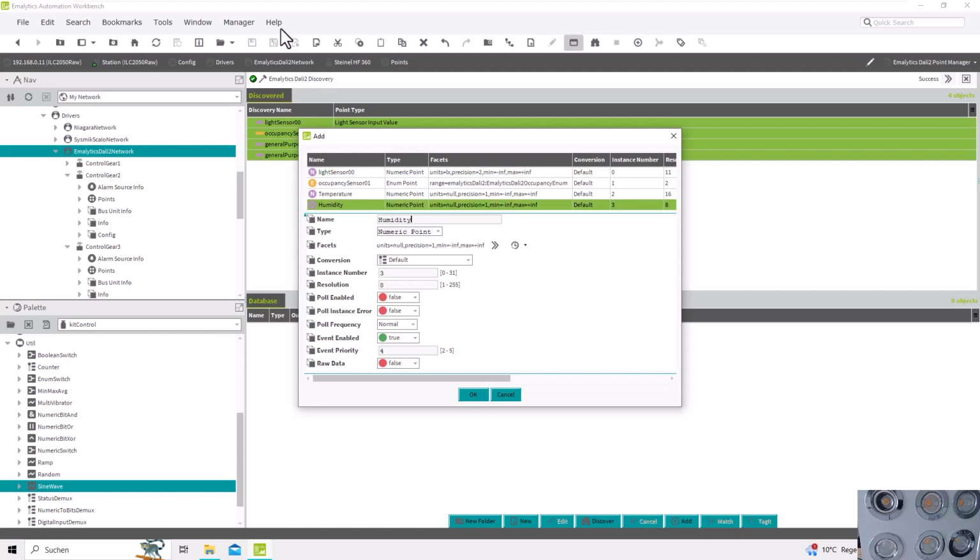In the DALI standard, values are defined with a percentage value. Technically, this percentage value will be transmitted with a certain resolution. This resolution is different due to the sensor and due to the value. In your application, a light sensor you will normally need with a lux value and not in percentage. Because of that, we have to recalculate the percentage value and have to interpret it into the correct value. This raw data slot is for that.